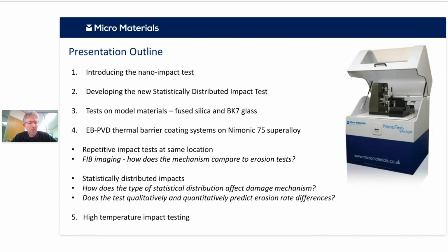Then I'll move on to looking at the E-beam PVD thermal barrier coating systems on a superalloy substrate. I'll start off looking a little bit at repetitive tests at the same location. Can we get the same damage from our test that we see in real erosion tests? So we've used focused ion beam imaging to get a handle on that.